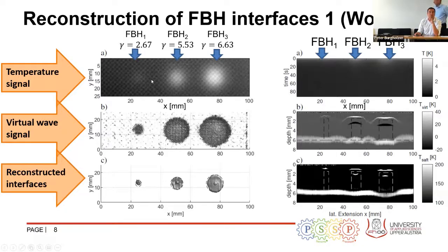And when you now do some ultrasonic averaging techniques, you get a very fine and very good contrast with the real defect shape in this result image. And this is the top view, and here on the right side you can see a cross section, and also you can see here the very good reconstruction result with a very high accuracy of the dimensions of the defects.